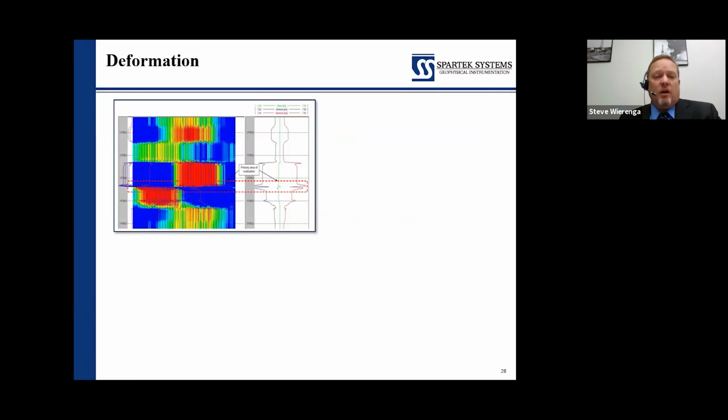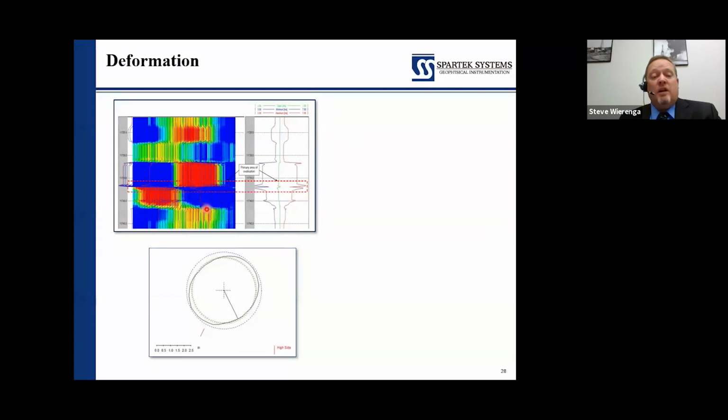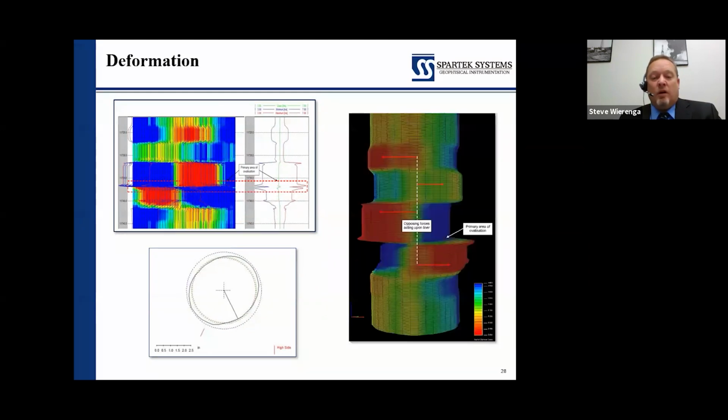Some examples here of what we would look at. So this is ovality. If we look at each individual finger plus a heat map laid in behind, just to see any changes, we see the min-max average, which shows us some differentials. But when we look at a cross plot, we can see that those differentials are in fact caused by ovality. So taking a look at that ovality calculation is very important, so that we don't mistake that for defects.